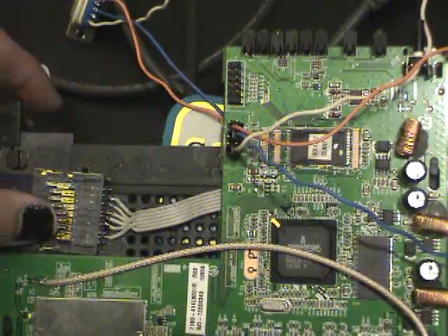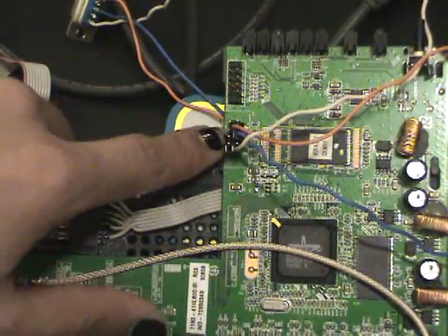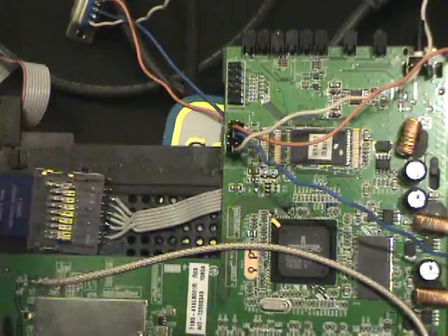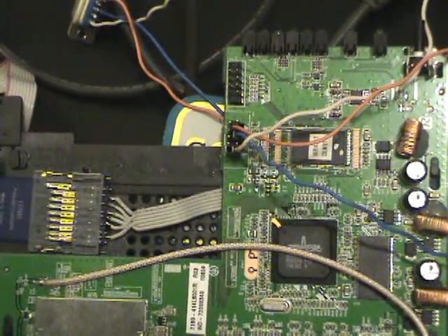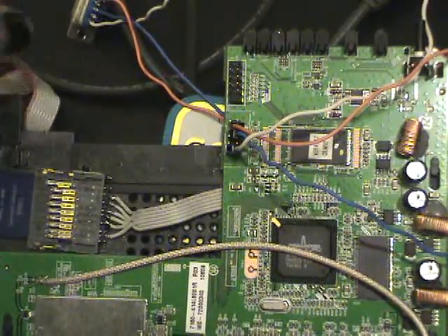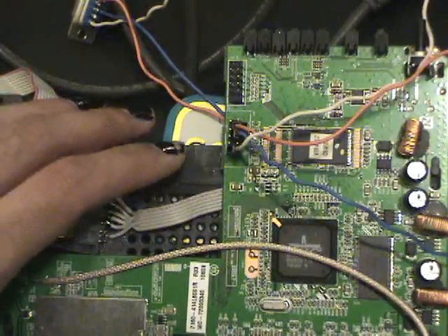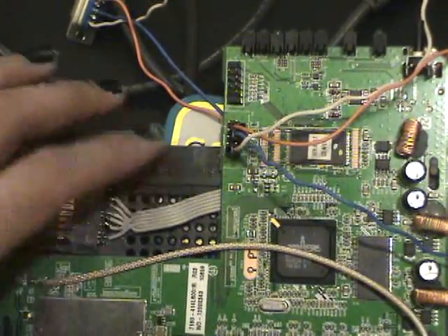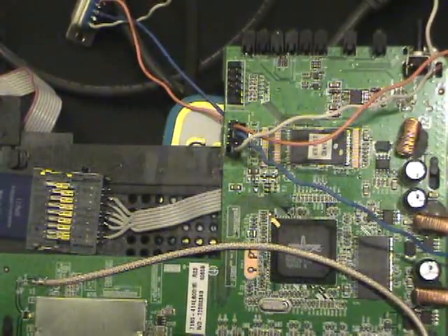If you go back a couple of episodes to my Salvaging Electronics with a heat gun segment, you'll be able to go and find the available components to put this header back in place, and then if you can run DD-WRT or OpenWRT, which will be a later segment, you'll be able to actually communicate with this port to create yourself a very, very naughty little device. Let's go to the software side and communicate with the WRT54GL via serial.